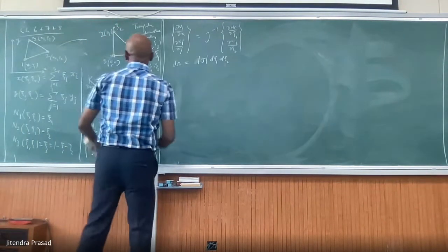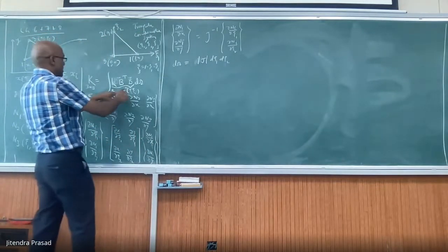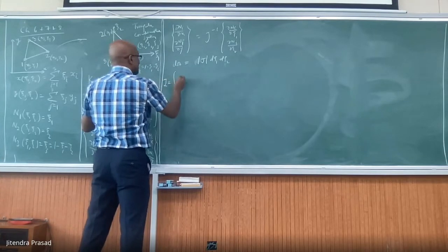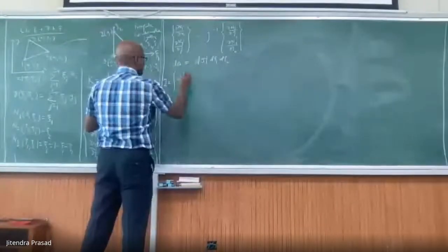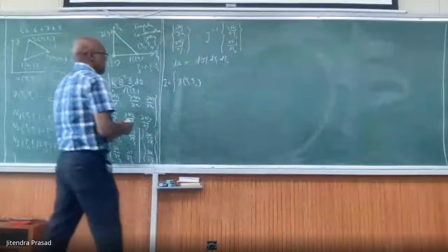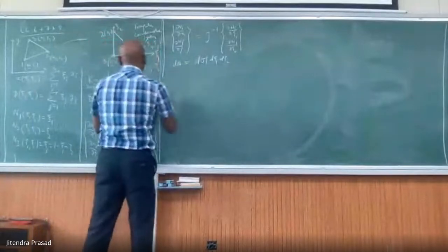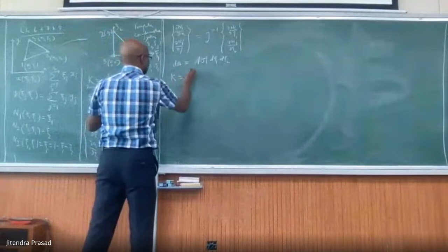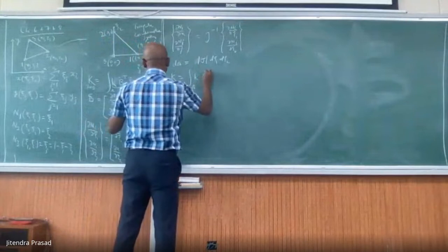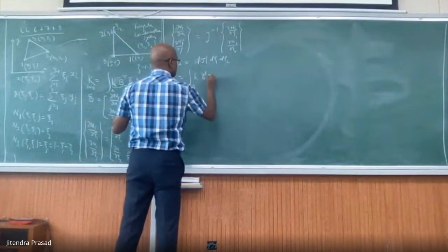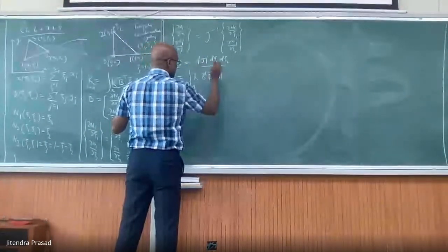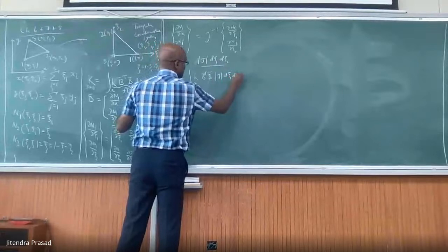Yeah, and then the rest is, let us say you are going to some function, let's call it g xi1 xi2. Okay, so here let's write small k becomes B transpose B, and instead of d omega you have J d xi1 d xi2.